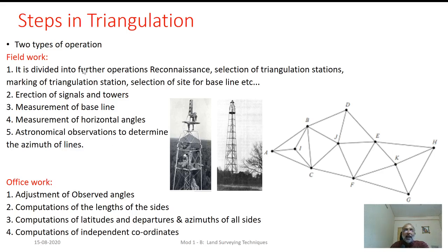Here, as we are dealing with geodetic surveying, we won't deal with magnetic north but with true north, and the bearing so measured will be named the azimuth of that particular line. So some specially designed Laplace stations, and observations taken to astronomical bodies like the pole star or true meridians, were essential as far as this framework is concerned.